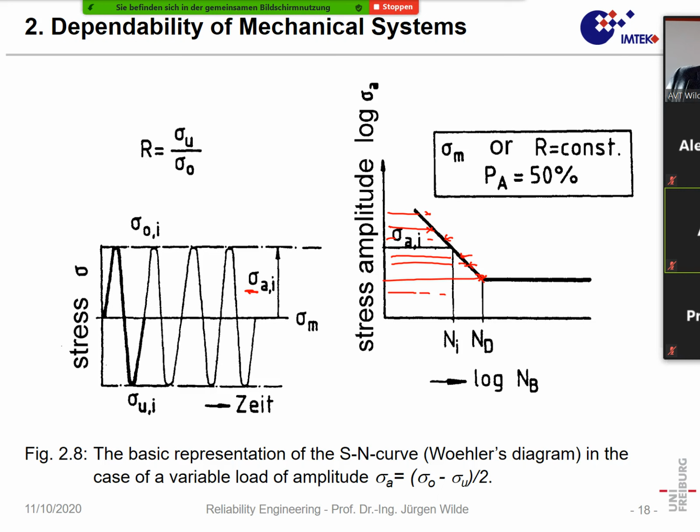But at a certain stress level, you can sometimes find you can test almost until infinity. That means then you have reached some kind of fatigue limit below which there will be no more damage. Fatigue limit is typically in materials when there is really only elastic deformation and there are no more internal movements or reactions in the chemical structure. And in that way, Mr. Wöhler could construct such a curve.